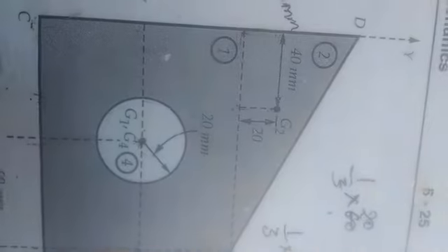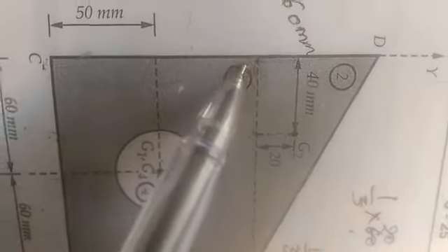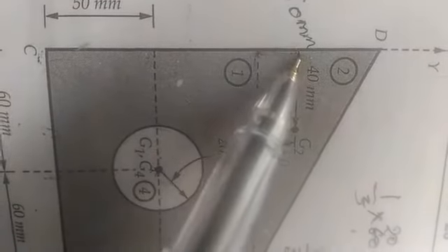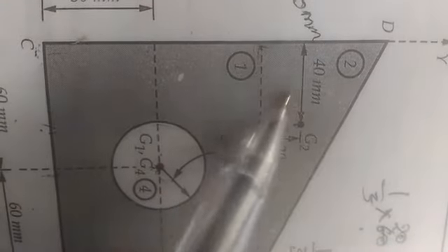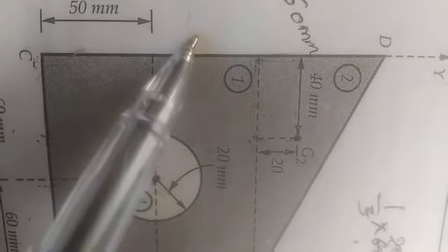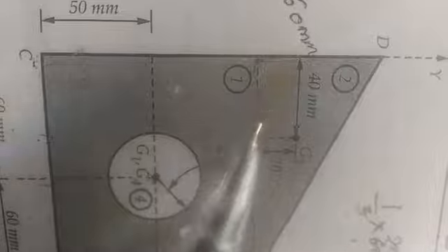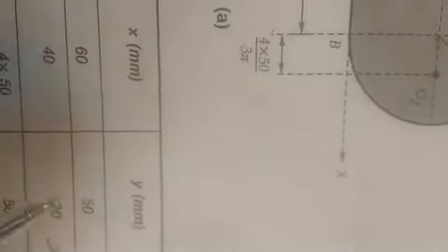But if you take the CG here, it is very far away from the origin. So this total height is 100 plus 20, so y distance would be 120. 40 is the x distance, but y distance is this plus this one, so 50 plus 50 is 100, plus 20 is 120. So that's why for the second one y distance is 120. The x coordinate has been written as 40 and 120 for y. Okay, second one is finished.